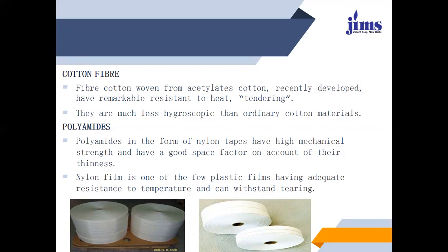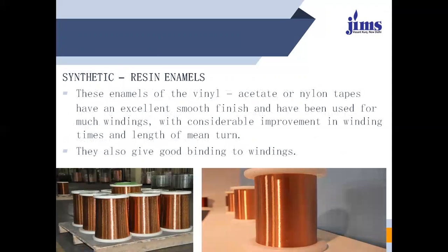Next is the polymers. Polymers in the form of nylon tapes have high mechanical strength and have a good space factor on account of their thickness. Nylon film is one of the few plastic films having adequate resistance to temperature and can withstand tearing. So this is the example we find in the picture, these are two figures of the polymers available.